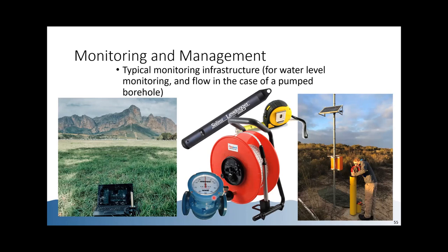We've spoken about flow meter, monitoring the volume. Another nice to have, and critical in some cases, is a water level logger, water level pressure transducer. What this does is this sits in your observation pipe or in your borehole, and it measures water level at a programmed frequency. So Solinst is a Canadian product that we commonly use in South Africa.